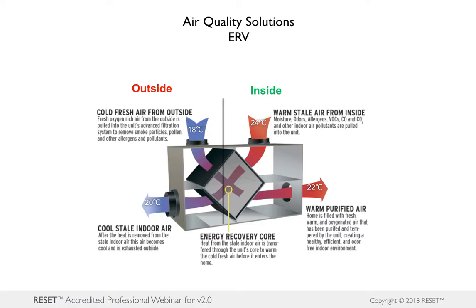So basically, it's a box where stale indoor air bypasses fresh outdoor air, and they don't mix. There's no mixing. But in the process, it does this energy exchange, or recovery, hence the name, so that you don't have to be conditioning the air from its most extreme states every time.